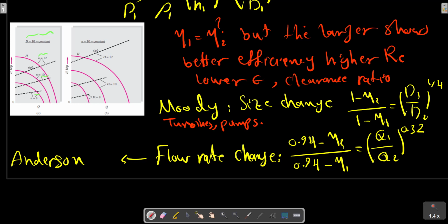The other is Anderson's, from thousands of pump tests. The Anderson formula makes the practical observation that even an infinitely large pump will have losses. He does propose a maximum possible efficiency of 94% rather than 100%, and also recommends that the same formula be used for turbines if the constant is changed for turbines.